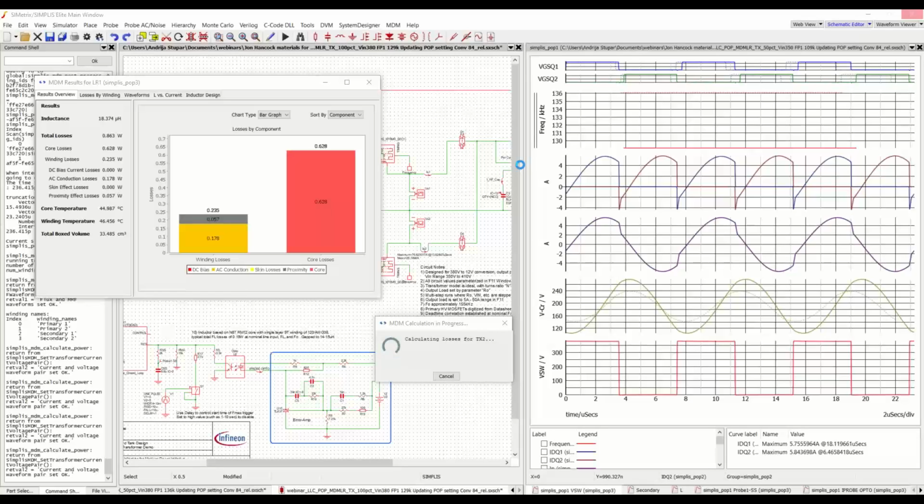So we would divide the core up into sections for which we can reasonably assume to have homogeneous flux density. This gives a small number of sections per core, something like 6 sections per core half, or it varies based on the core shape, but it's in that range. It's not like 50 or 100 or something. It's in the single or low double digits.